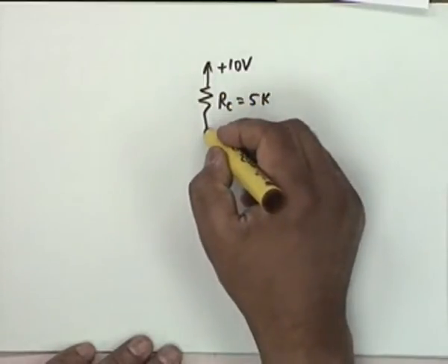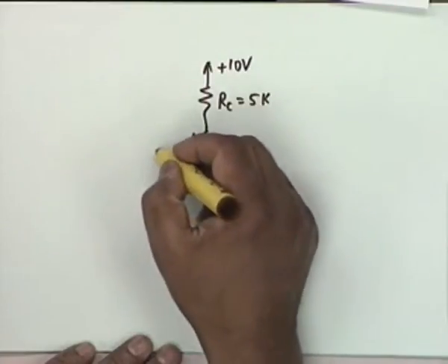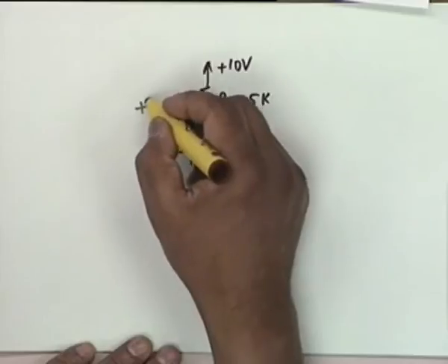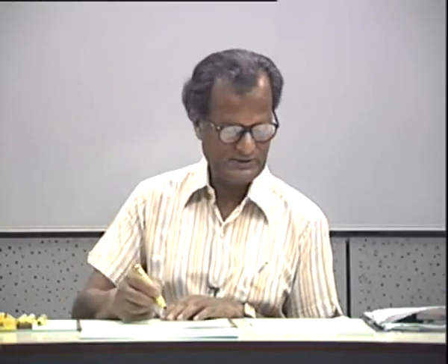You have the transistor Q2, the base is maintained at a constant voltage of 1 volt. Okay, the base biasing is not shown, it's maintained at a voltage of 1 volt. Perhaps a 7.2 volt Zener and then a potential division, perhaps of that type. Okay, we don't get a 1 volt Zener. 7 is perhaps the minimum. No, there are smaller voltages also.